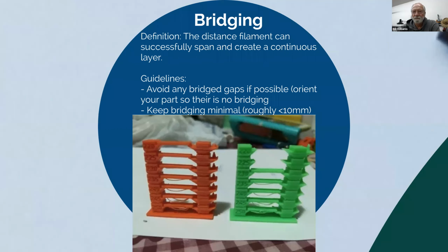Dana, go ahead. I have 2 questions. One, when you're talking about the 45-degree angle, why can't there be support structure under there? I mean, you can put support structure under there and make the base larger, right? Absolutely. Yeah, and again, these aren't rules, these are just guidelines. These are guidelines to make the best quality part with the least amount of post-processing work.